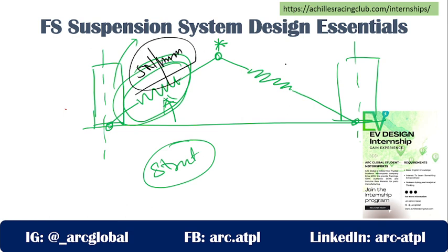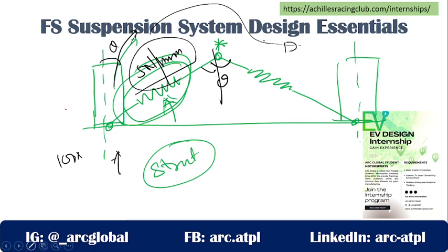The suspension system stiffness. And accordingly, you will be finding out at what force, not just at the distance, I apply 100 Newton, how much will my tire move up? How much will my tire move down? At what camber angle will it be? My dear friends, you can do the same thing for the texture.